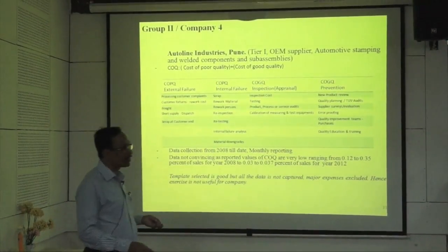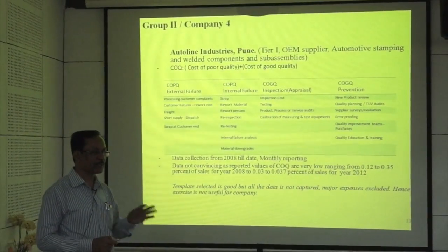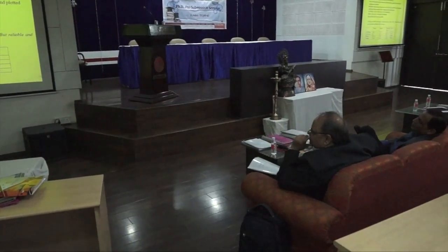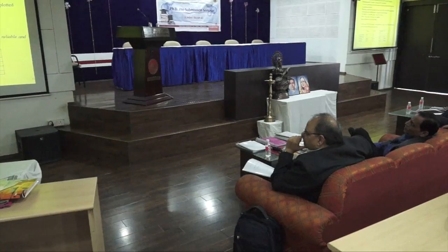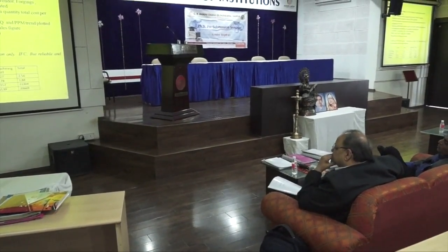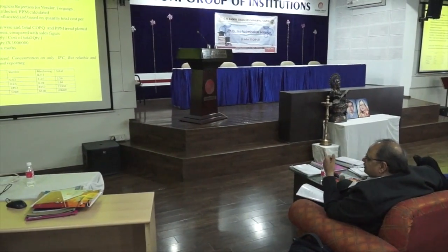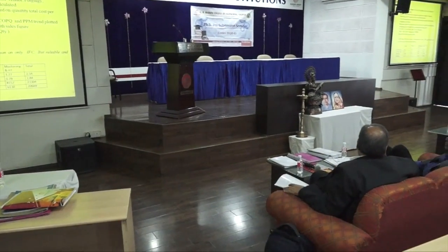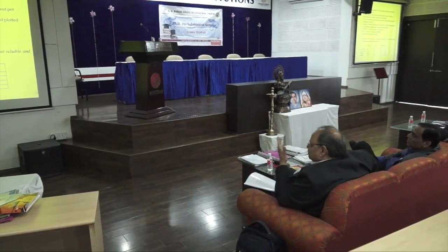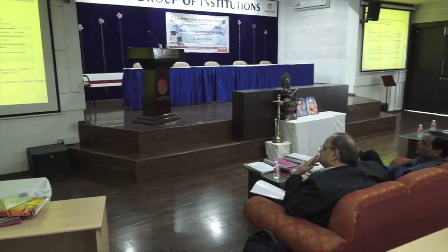Now, the auto line industry, some other thing I have observed here, they do all the jargon of cost of quality, but they keep it separate. When you say forging rejection, are they the basic forging only, or after rough machining also? No, basic forging only. And then after that, rough machining, HT, and then final finishing. So that's why rejections are more there. Yes, rough machining is also taken in machining. Even foundry rejection is there. All those forging component rejections are also not done there.